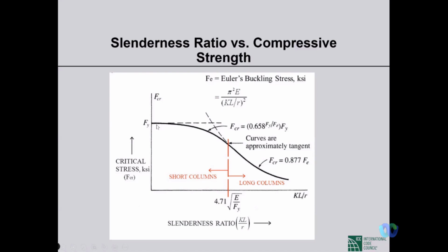In terms of moment, we call it plastic moment Mp. In terms of load also, you can call it that, that is completely plastic. The whole section becomes plastic. So this is the case, and in between these two, that is elastic buckling and plastic case, there will be a transition, and that transition is shown with this complicated equation, 0.658^(Fy/Fe) multiplied by Fy.